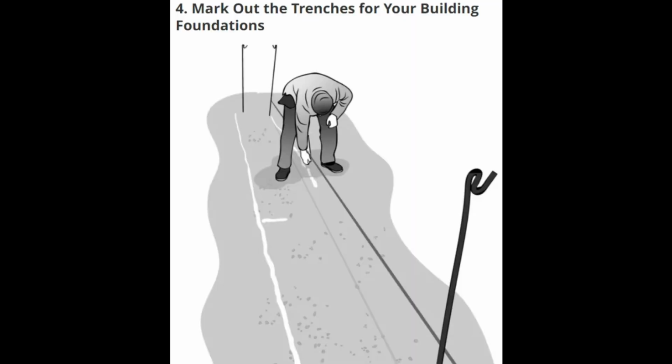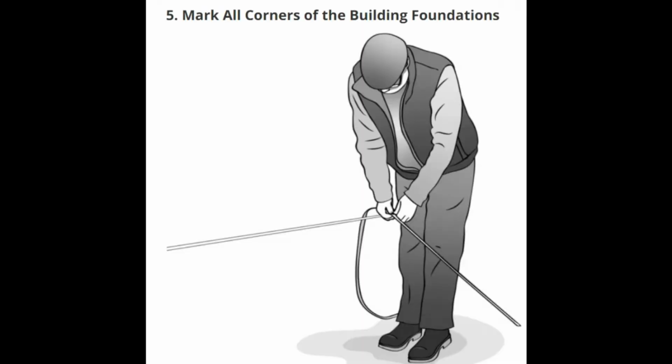4. Begin lining up your footings by referring to your datum point. When it comes to extensions, never assume an existing building is square. Pick the side you need to be square to and set up a line, then square off that line. 5. Once you have two lines set up at 90 degrees, all other measurements can be taken from this point, with all corners and junctions marked. A lot of digger drivers are quite happy for you to mark center of dig lines, but you may prefer to mark both sides of the trenches.